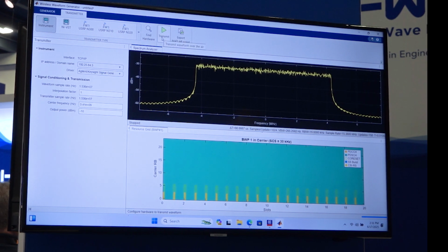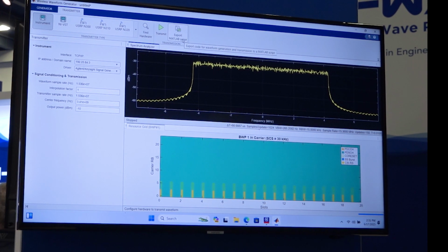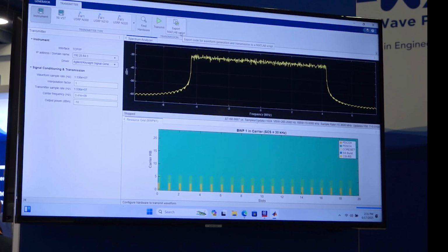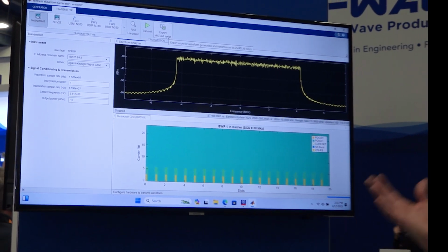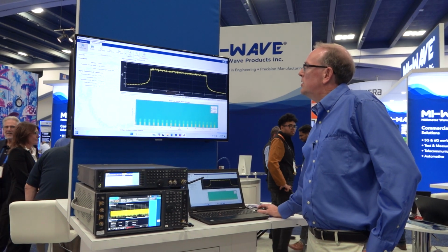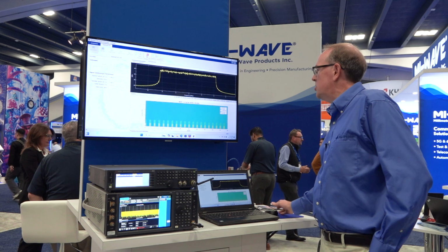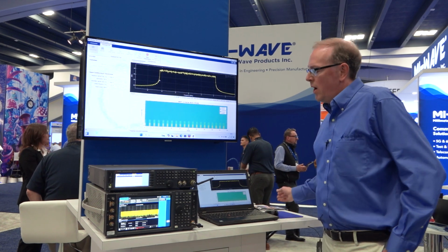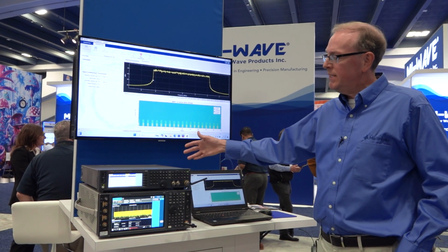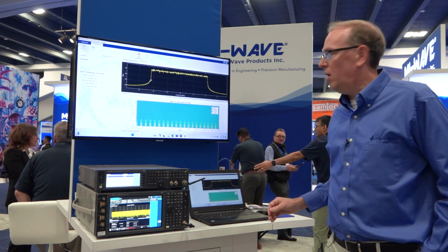But before I hit transmit, it's important to note you can export a MATLAB script that will give you the MATLAB code that contains the signal content as well as the instrument connectivity. So I'm going to transmit the waveform. And now the waveform is being downloaded to the instrument. In our simple setup here, we're basically sending a signal over the air from the generator to the analyzer.